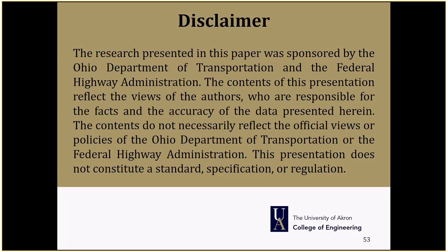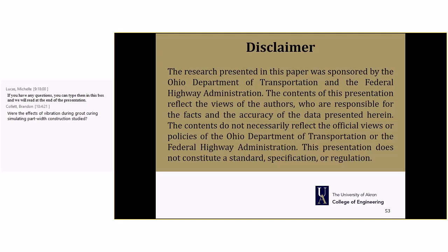So on some of the projects that we went to review the contractor's work, the preparation of the top of the box beam was not very good at all. Many shards. Contractors routinely would take paving equipment directly on top of the membrane, there may be aggregate on top of the membrane, and the construction practices really didn't do anything to protect the membrane. And on one project where I saw the information, there were probably hundreds, if not even 1,000 penetrations through the membrane before the paving was even down.